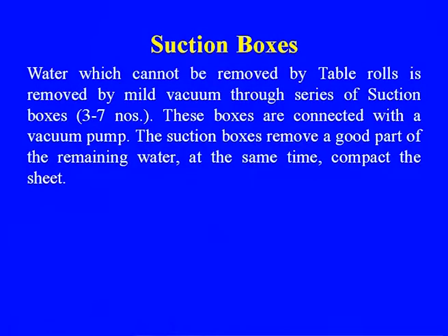Suction boxes apply vacuum for removal of the remaining water, because 100% removal may not be possible. So, we need this vacuum for removing the remaining water. The number of suction boxes may vary. These boxes are connected with a vacuum pump. The suction boxes remove a good part of the remaining water and at the same time compact the sheet.